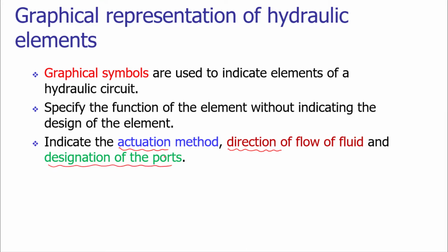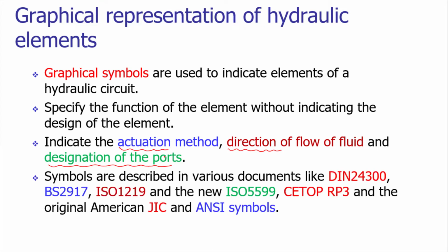So we have seen that various types of external openings are there on the valves, and these ports are to be designated. This may be the pressure port or the application port, or they may be the tank port or the sump port. To standardize this communication, to standardize the convention of providing the graphical symbols, various guidelines are available,